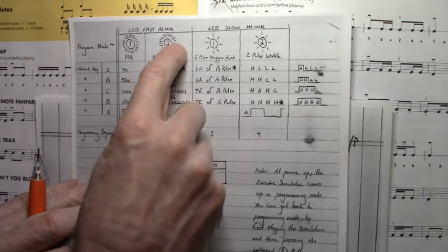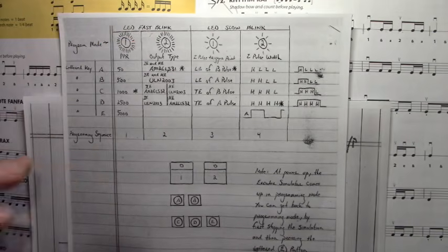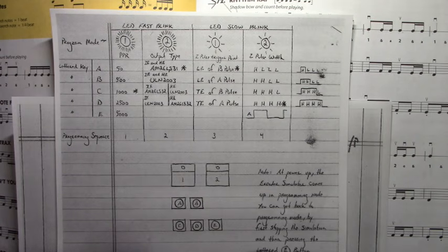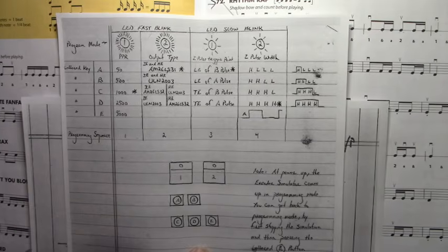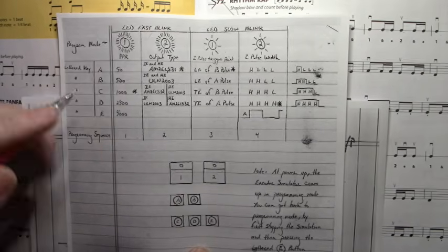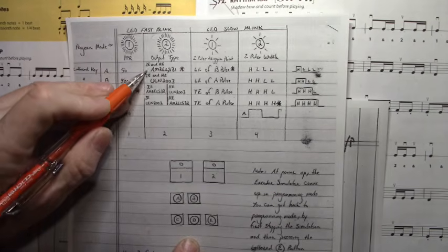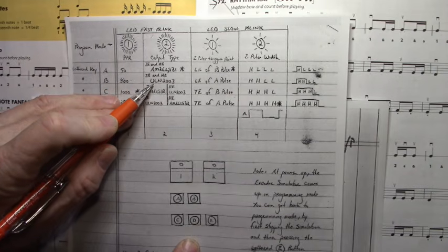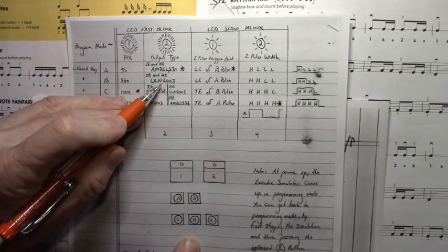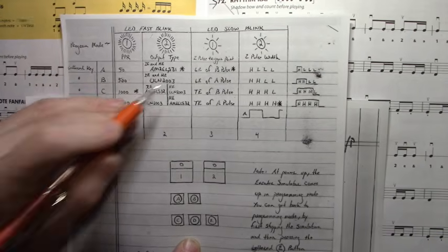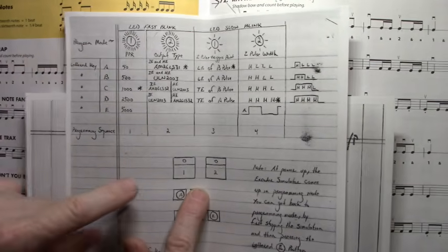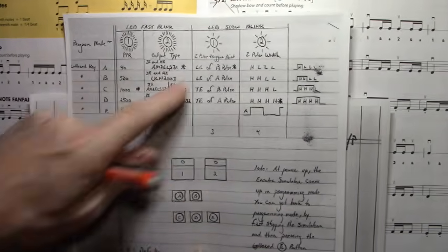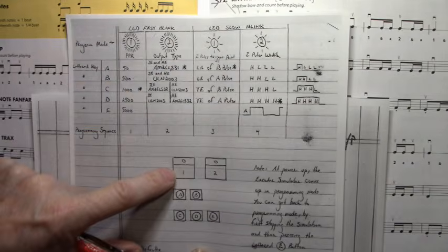And so now we're over here on switch number 2, blinking fast. That's a visual indication to us as to where we are in the programming process of setting this tester up. So now let's say we want incremental encoder and Hall effect to be processed to the output, the open collector output ULN2003. We would push the B button right here and then push the number 2 switch up here. And at that point we'd be over here with the number 1 switch again, but blinking slow instead of fast.